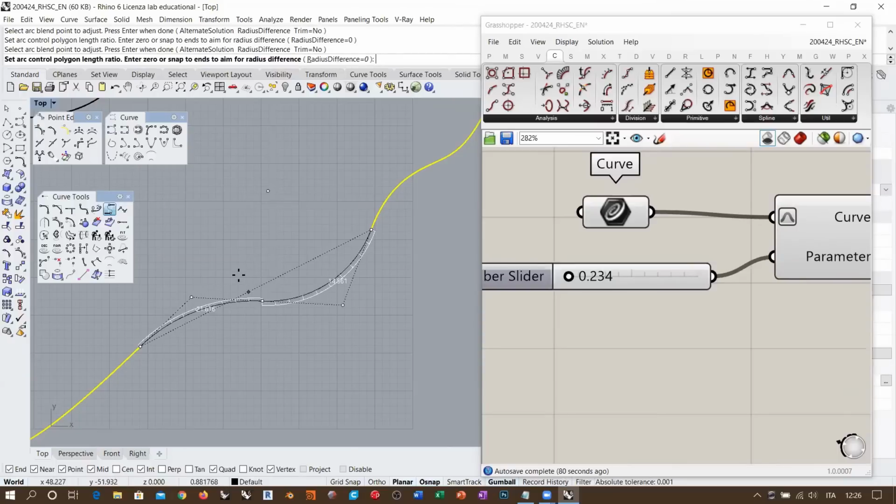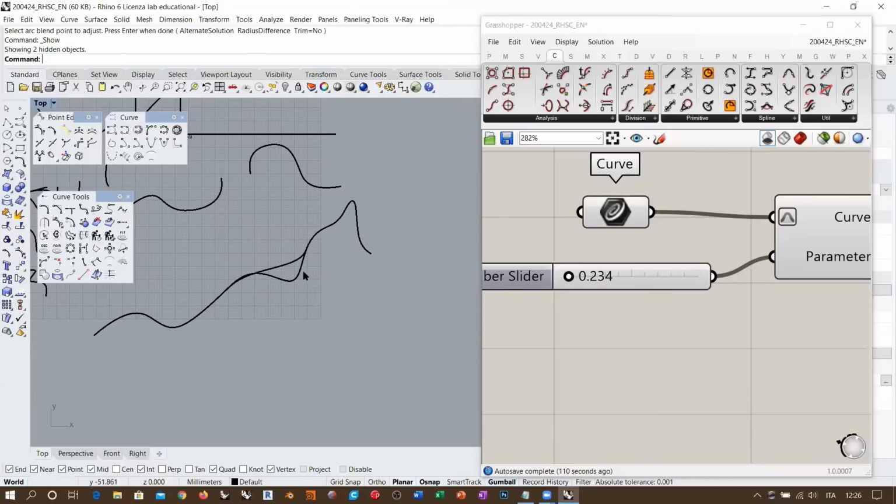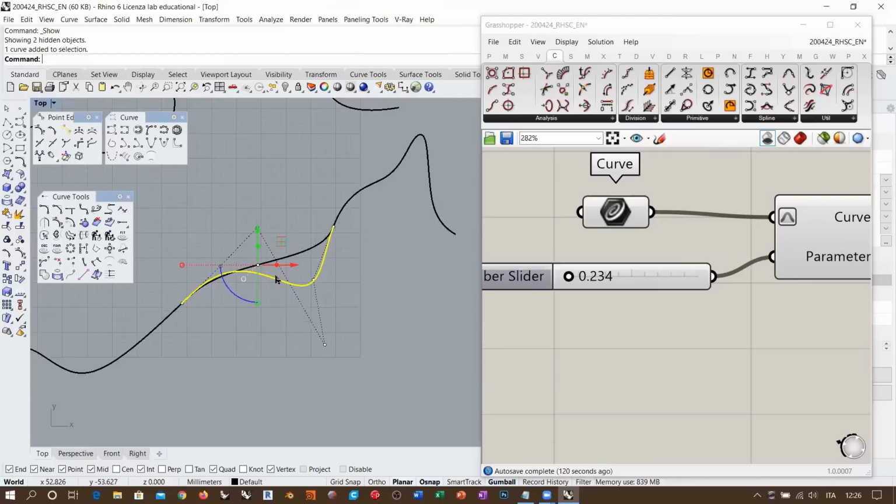This means that you can create this blend curve, which is going to be smooth, well, not smoother, but with less curvature, of course, than the blend curve. But you have more control of this, and this is more useful in terms of production, okay? Because this is very easy. You know that you can only pick the center point here and the center point here and trace this arc and this arc, okay? So this is good for production, whatever type of production you are into, okay? While this one is extremely nicer in terms of geometrical aspect, but it's more difficult to construct.